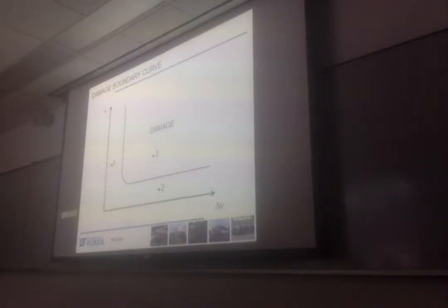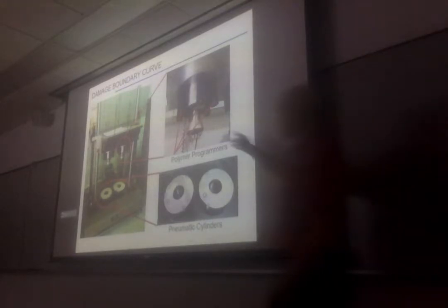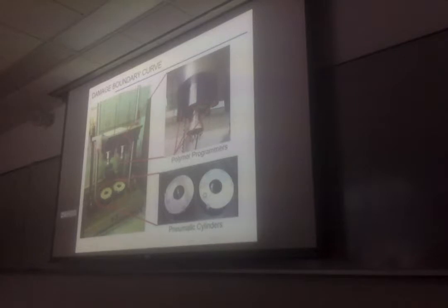So, yes. I don't understand how the product experiences that one versus the bottom one. So this versus this? Yeah. On the table itself, there's an accelerometer that is bolted on the table, okay? It measures acceleration. So if you drop the test and you create an impact on those plastic programmers, the acceleration when the table hits will look something like this.